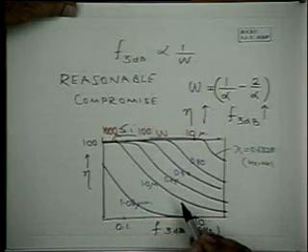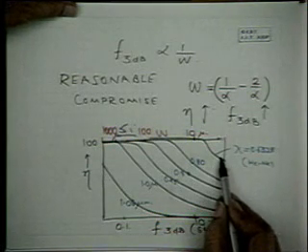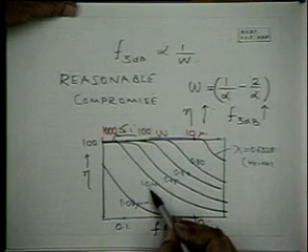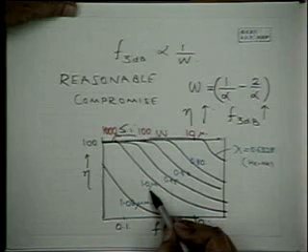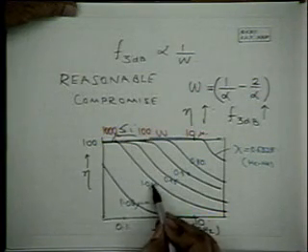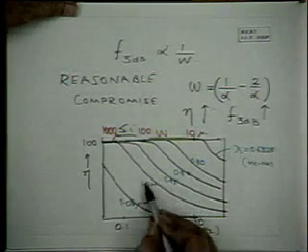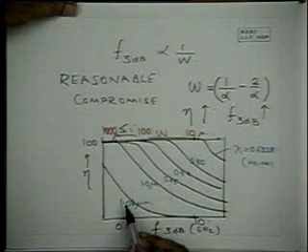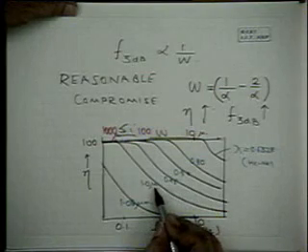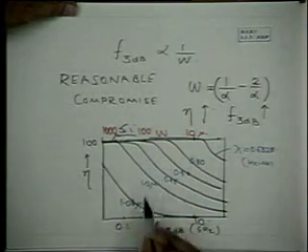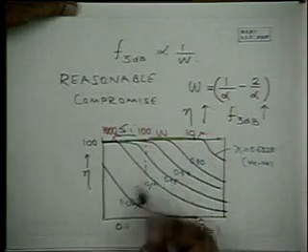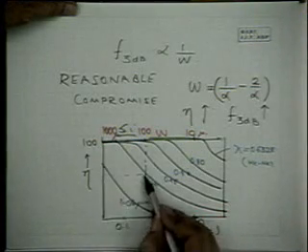Now suppose you take longer wavelengths. At 1 micron, the absorption alpha is much smaller. So if alpha is much smaller, quantum efficiency comes down, and we find that the response is like this. The F3 dB is then for a given value of W somewhere here,